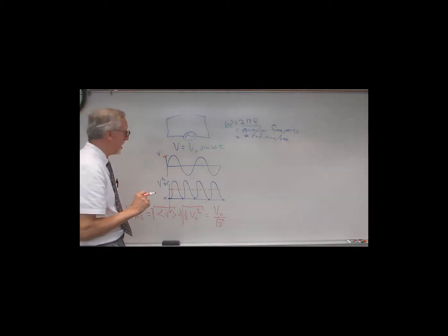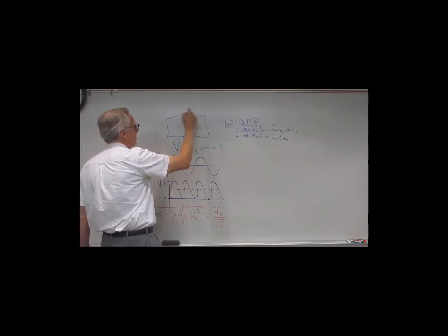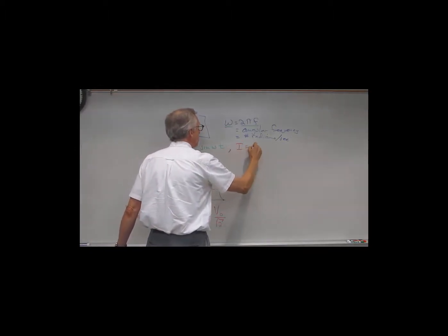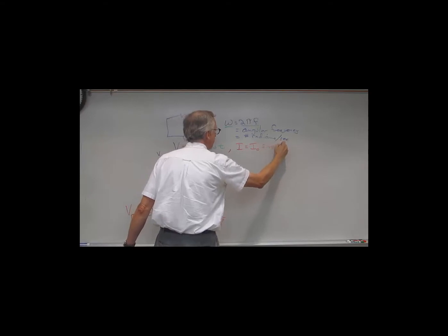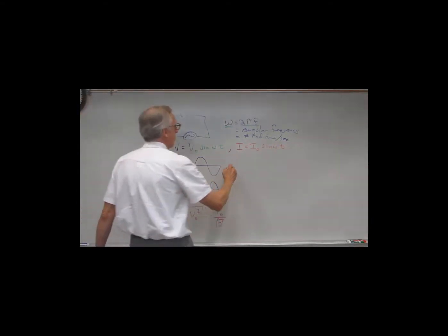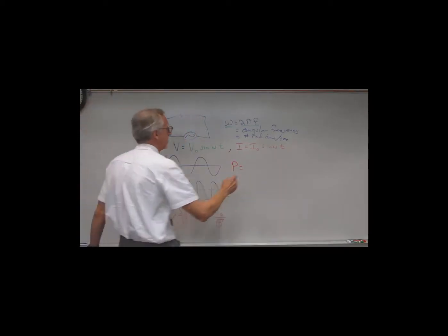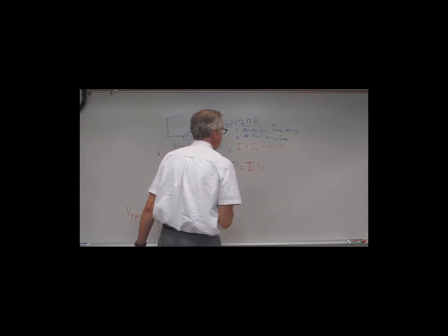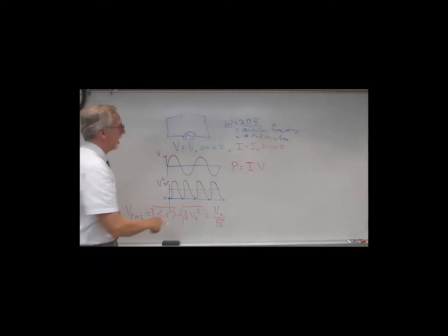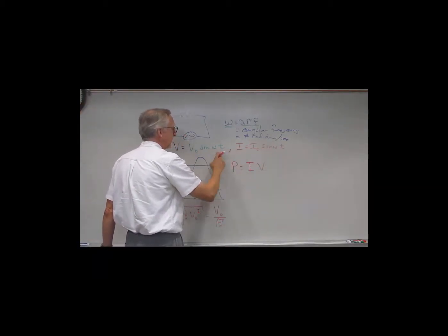We'll see this more later on, but let me just mention, for an oscillating voltage, if we were to put just, say, a resistor in here, we would likewise expect the current to have some oscillating form, like I naught sine omega t. Well, what would the power be for this circuit? Well, we know the power for any circuit we could write as IV. But what would the average power be? Well, the average power will go like sine squared, I naught V naught sine squared.